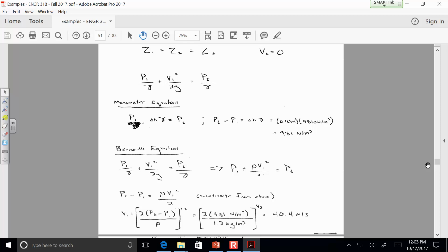It's just in the liquid section that the pressure is varying appreciably. So this differential manometer is telling us the difference in pressure, but then it's also encountering those dead-ending streamlines, which allows us to capture the velocity head as well.